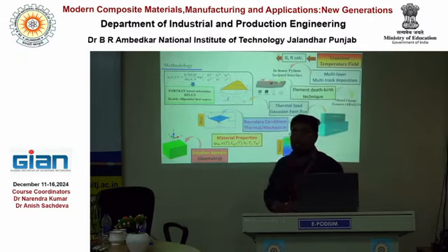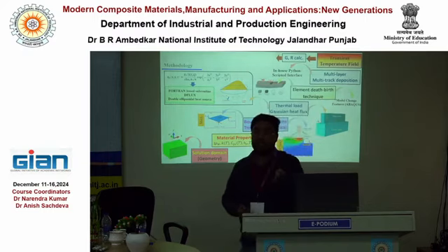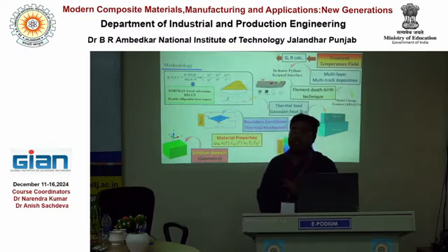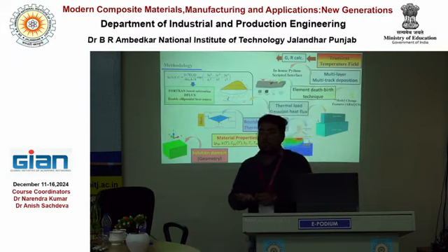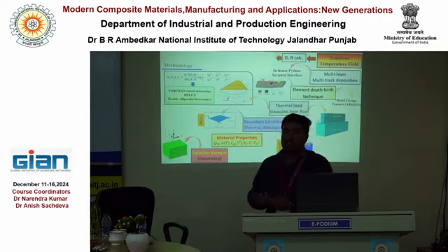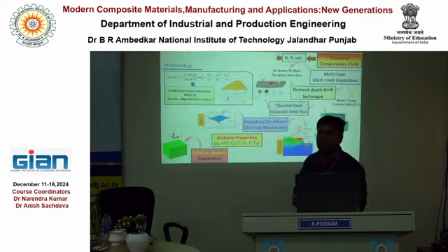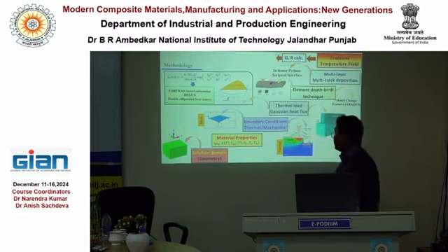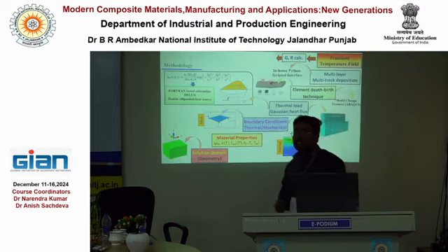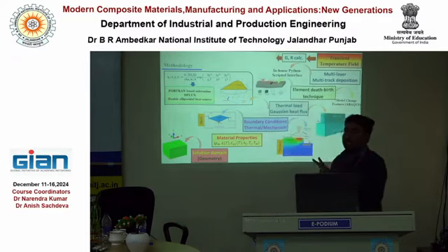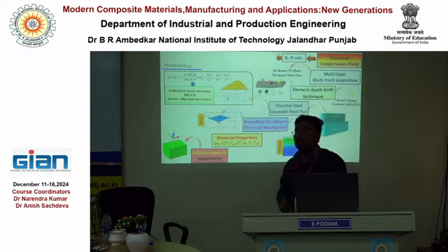That is very crucial in order to predict the microstructure as well as the mechanical and functional properties, whether it is tensile testing, hardness, microstructure, metallurgical properties, or any other thing. So we need to take care of the solidification parameters, G and R. G is the temperature gradient and R is the solidification rate, and if we multiply these two factors, we can calculate the cooling rate.